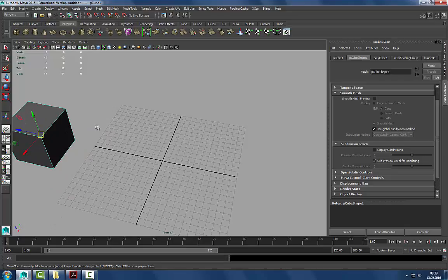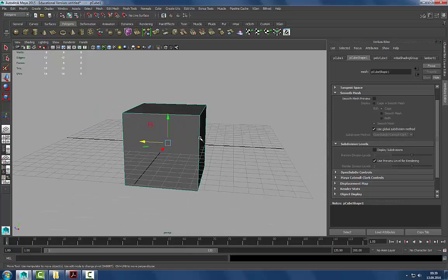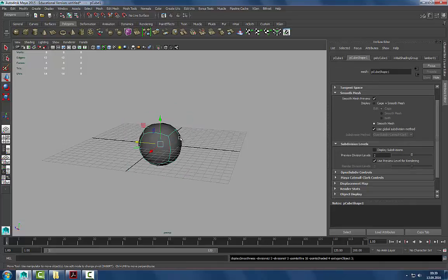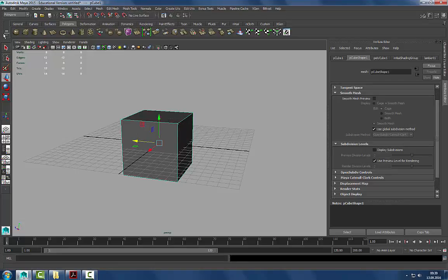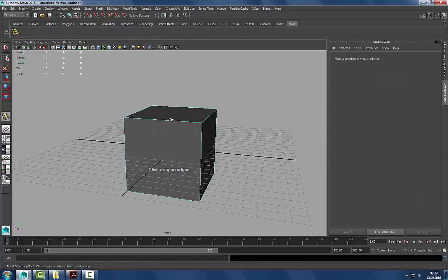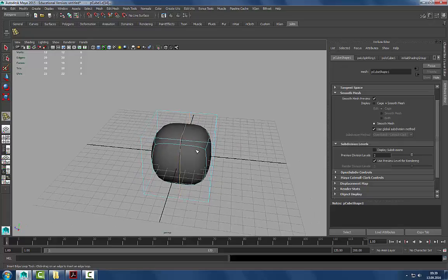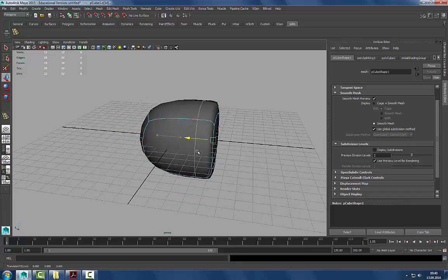And there's a few benefits to doing that versus using surfaces. So now we have all these vertices. They're spaced evenly apart. It just causes this rounded off effect. But we could go to the insert edge loop tool again. Let me just find it. Sorry about having to do this over and over again, but at least you see it again. So insert edge loop tool. If I just freely place an edge and press number 3, you see that, okay, that has an effect on the subdivided result. I can move that edge around so we can see what it does.